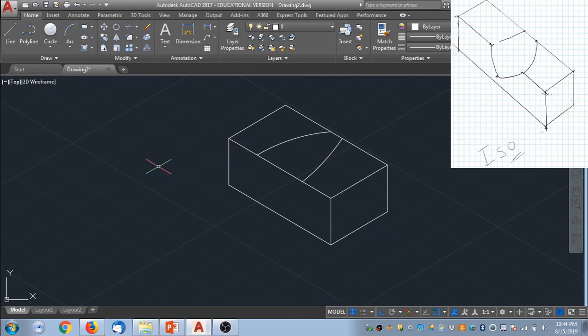And that gives us the top, and we'll do the construction lines for the bottom, but we only really need the middle one. Hit F5, switch my axis around so I can go up. I can draw a 1-inch line up, and now I can use the arc tool to arc in. Yeah, cut out. Trim the arc down.